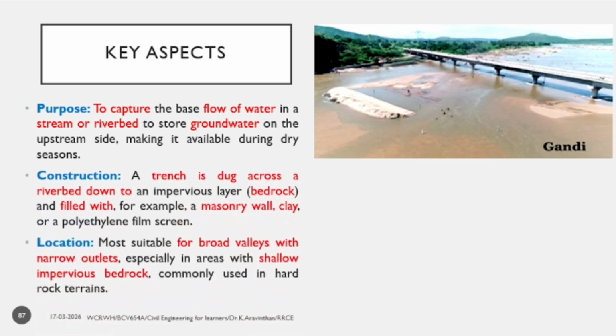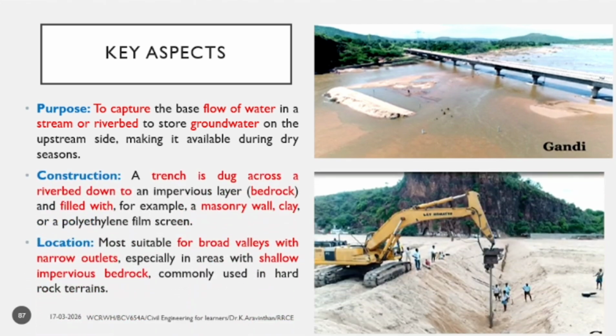Next thing is, can you see here? They are digging the sand by using a JCB. After excavation, what they will put is sheets. They are called waffle sheets or Z sheets. Construction is, they will construct a trench below the bed of the rock. Till the bed of the rock it will be driven. Sir, how many feet? It depends on the geology of the place.